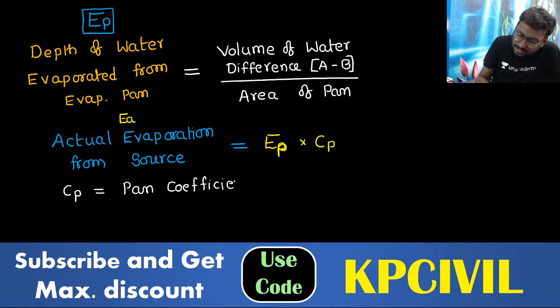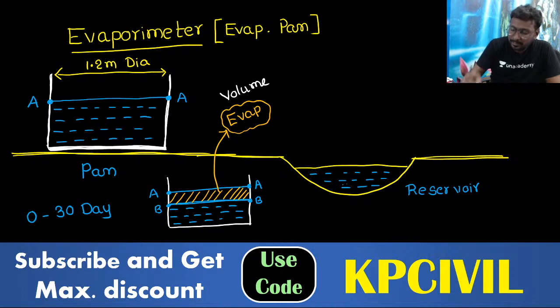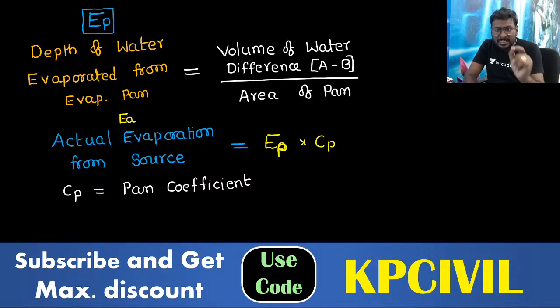Pan evaporation is more than actual evaporation, because that is a restricted area. We are imparting forces into a small area, so pan evaporation is going to be higher than actual evaporation. Ramakrishna, you got it? In a small container we are restricting, but in a wide area it is going to occur. In such a case, you are applying values from a small container to a huge area of reservoir. In such a case, the forces acting, all these things will be different. That difference will be taken in terms of the pan coefficient.